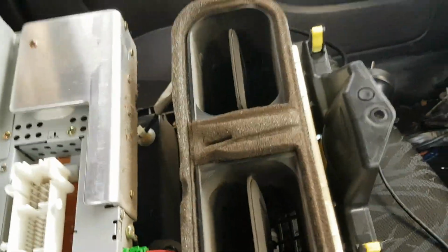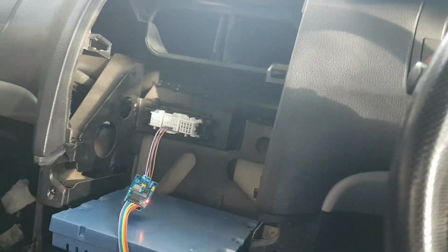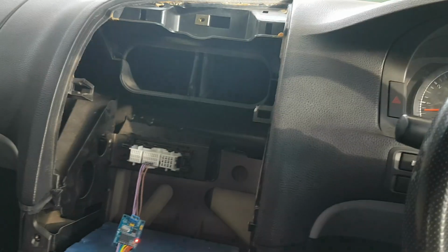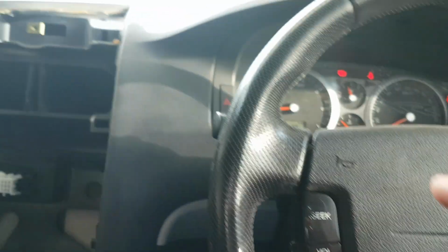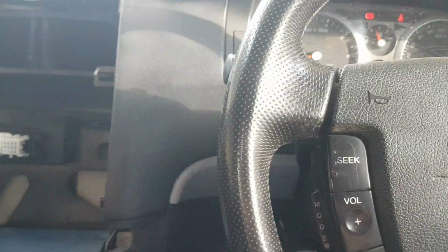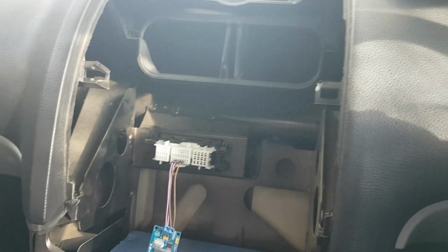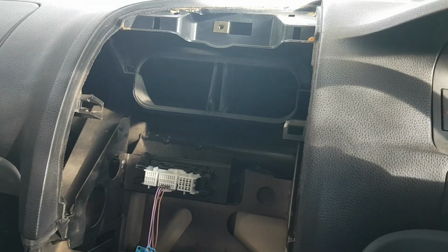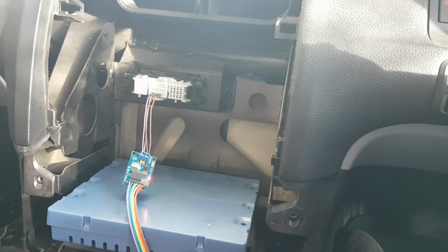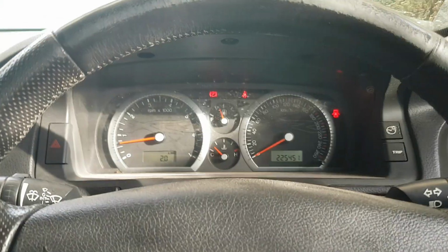So the interesting thing is that the ICC mustn't have anything to do with the security, as far as PATS, passive anti-theft system, because it's completely removed, and when you remove that, it breaks the link between the BEM and the cluster, so they can't communicate at all. So that's good news that whatever head unit I design and put in there, it won't interfere with the security of the car, which is great. Yeah, anyway, that's it.